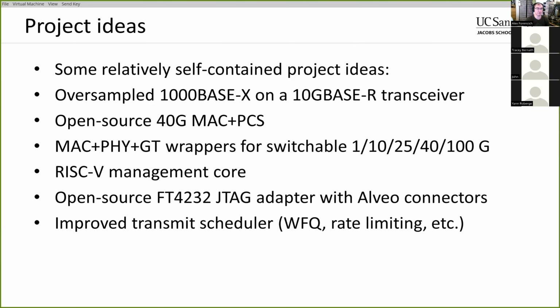If you use different soft cores, you might need to change some aspect about how that interface works. And these days, you can get some very, very small RISC-V soft cores to put down. Like I think the VexRiscv in particular can be configured to be quite small and efficient. This doesn't have to be very high performance.